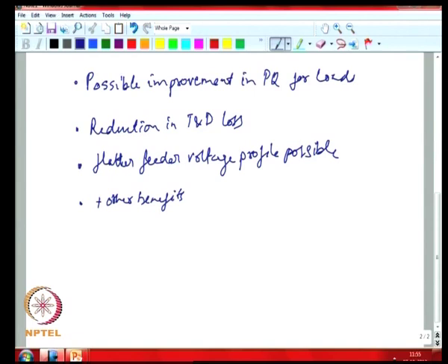So, you also need a large number of switchings to be possible, and if you look at all these requirements of limiting fault current level, fast power control, and need for rapid switching of the interconnection device, all those imply that you would have an increased role of power electronics compared to the existing traditional systems that can be used for interconnection. So, the role of power electronics in distributed generation would be increasing as we proceed in time.